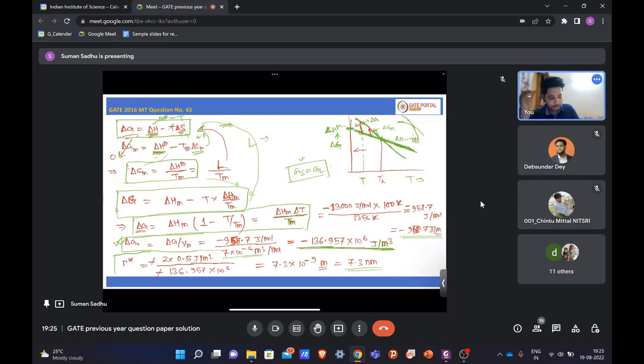Now you can see that if you are at this point where Gs is equal to Gl, you don't have that available energy that you can give to form a new interface. So you have to move below the Tm, so that you will have a difference, this delta G, that is Gl minus Gs, or Gs minus Gl, product minus reactant kind of thing.